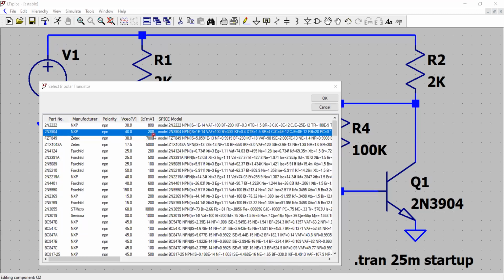The maximum current it can withstand from collector to emitter is 200 milliamperes. It is a SPICE .model 2N3904, and it is NPN, and we are interested in having the beta factor of 300. The rest of the parameters we have explained in several of our earlier modules, so refer to that if you are new.